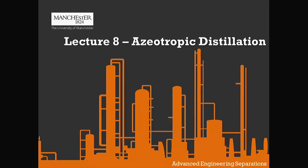So hopefully from the tutorial questions, you have an idea how we can either plot these residue curves accurately using exact information about the vapor-liquid equilibrium between all our components, or if we have just knowledge of the compositions and the temperatures of the azeotropes and the pure components, that we can look into creating an approximate set of residue curves, or at least find out where our distillation boundaries are.